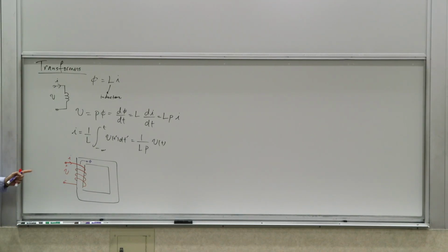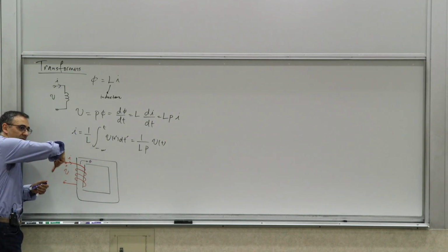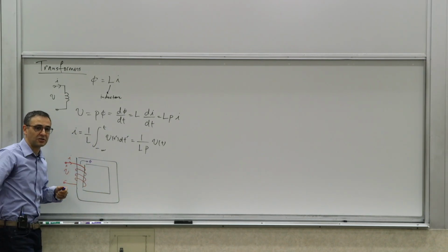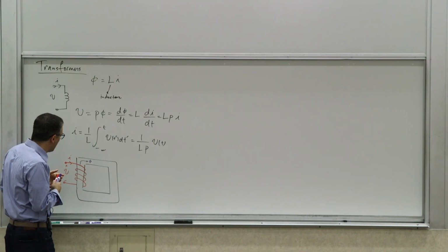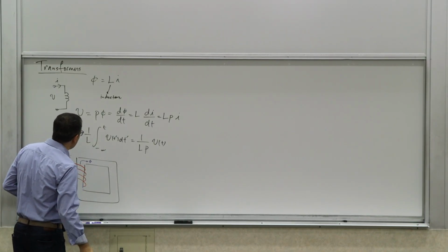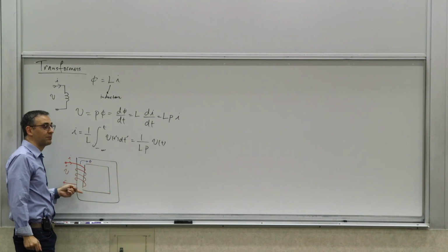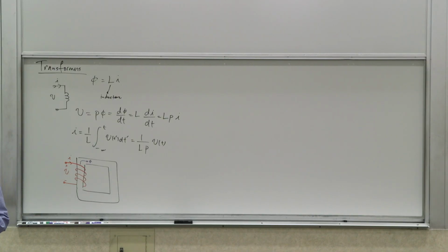So that, right? Because you can actually wind it the other way around. You can wind it in the other orientation, and then it would induce a magnetic flux that goes in the other direction. And we'll see in inductors this matters, which way they're wound with respect to each other, the direction of winding. So in transformers, this is an inductor. This can be a magnetic core, for example a pure iron core or something like that, a ferromagnetic core that produces a strong magnetic coupling to something else.